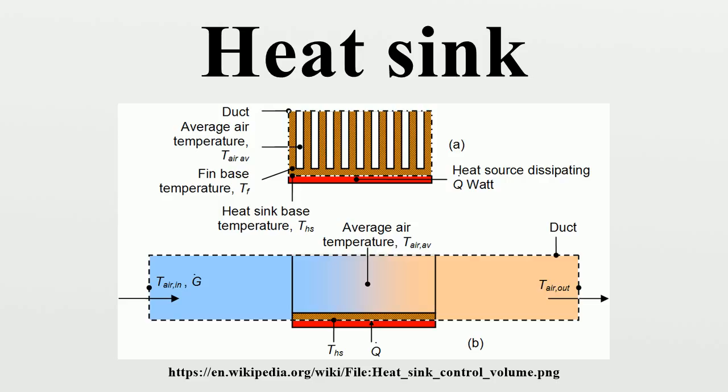The inlet air temperature relates strongly with the heat sink base temperature. For example, if there is recirculation of air in a product, the inlet air temperature is not the ambient air temperature. The inlet air temperature of the heat sink is therefore higher, which also results in a higher heat sink base temperature. If there is no airflow around the heat sink, energy cannot be transferred. A heat sink is not a device with the magical ability to absorb heat like a sponge and send it off to a parallel universe.